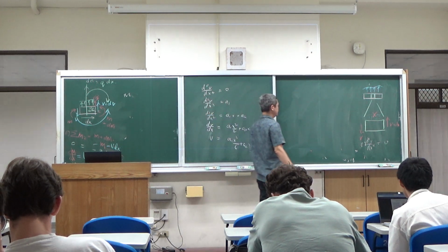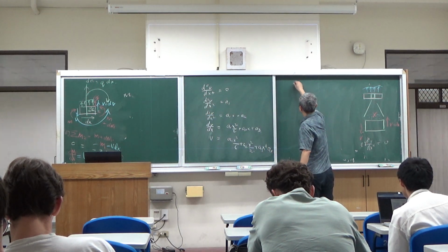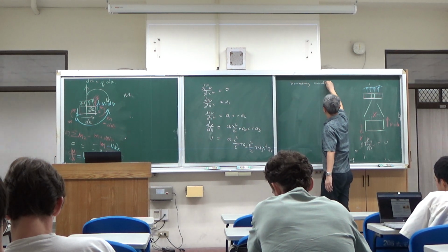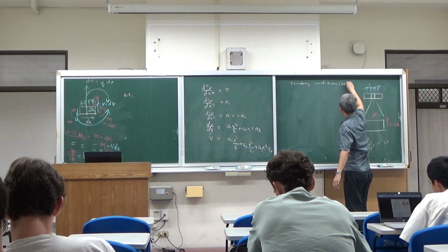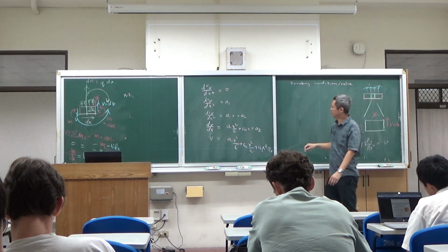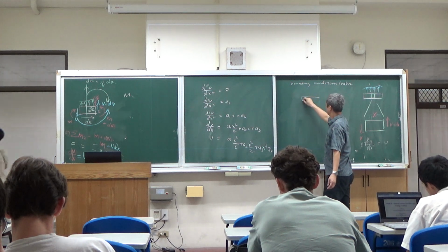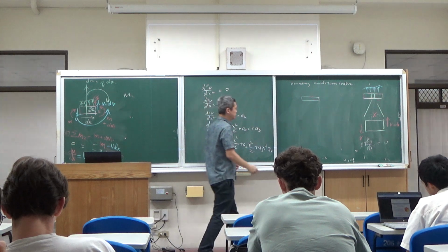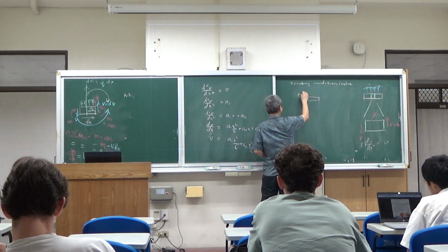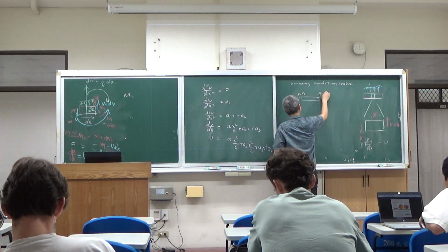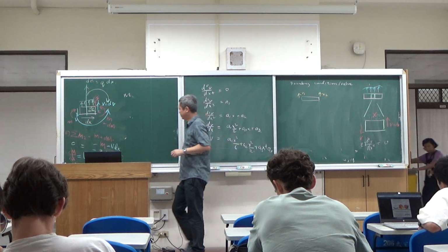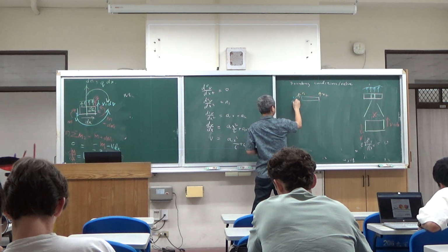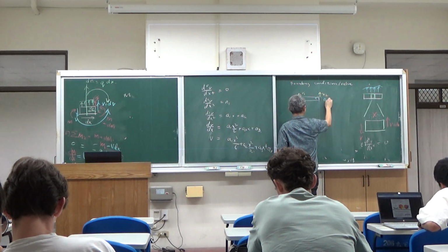So now come to the point of the boundary condition or boundary value. In the case of finite element, you want everything unknown to be defined as something known or to be solved. You could possibly have v1 on the left hand, v2 on the right hand, and then theta 1 on the left hand, theta 2 on the right hand.